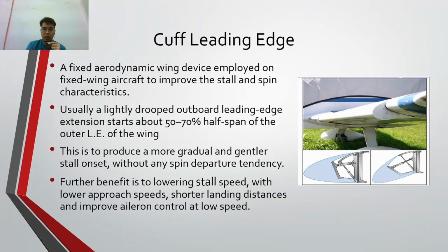The further benefit of curved leading edge is to lower the stall speed with lower approach speeds, shorter landing distances, and improve aileron control at low speeds.